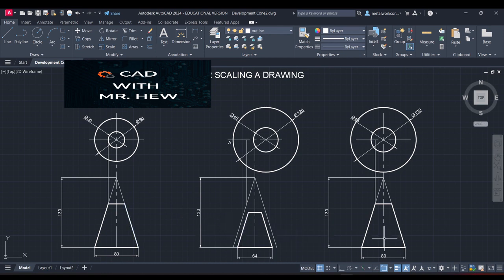All right, we're going to do the same thing here. So I'm going to type in my scale command at the cursor there. Select the objects there. Enter when I've completed. Now it's asking me to specify the base point. I'm going to choose up here as a base point. What do you think would happen if I choose here as a base point? Can you guess?